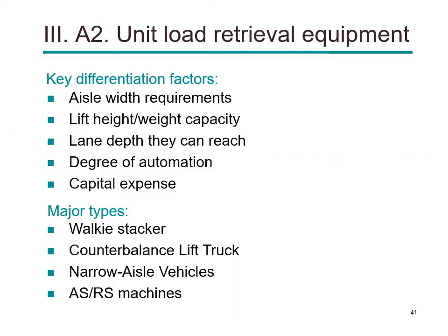After talking about these racks and unit load storage equipment, we can now talk about unit load retrieval equipment. In order to select your unit load retrieval equipment, or to compare the capabilities of different unit load retrieval equipment, we should consider these factors. What are the aisle width requirements? What should be the width of the aisle so that a specific retrieval equipment can operate? The lift height and weight capacity of the equipment. Lane depth that they can reach.